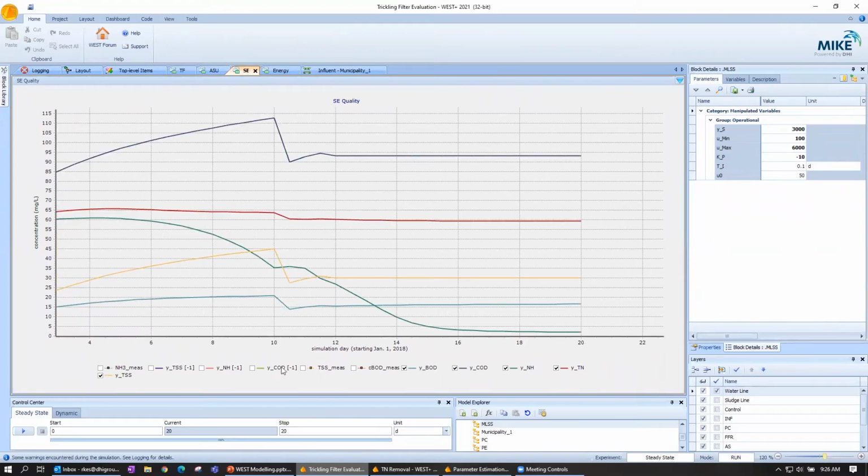We'll see what else happened. We also see that this yellow line, if I compare it to this purple, let's add some more things to make it more obvious. That's secondary effluent solids, TSS. And this was the run before when it was calibrated. So we went from around 12 to 30. So that tells me that I have to revisit that assumption about the secondary clarifier.